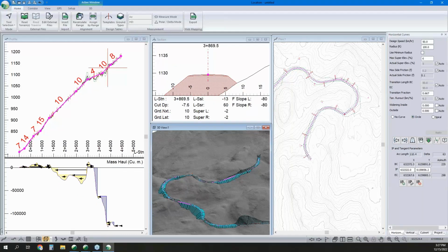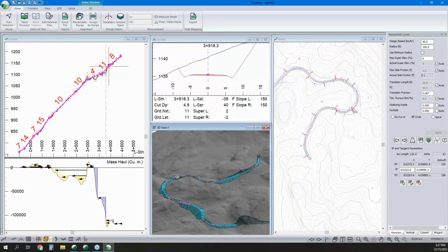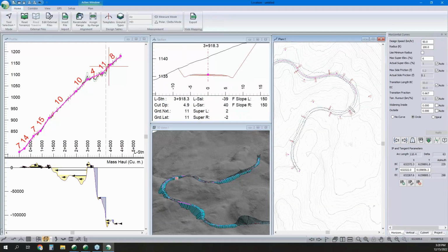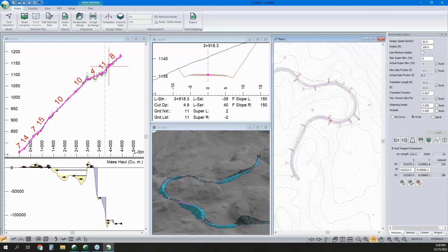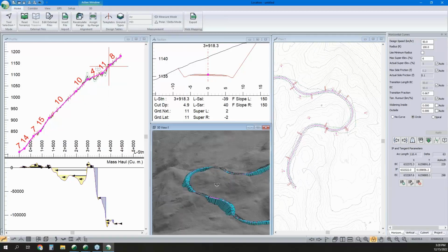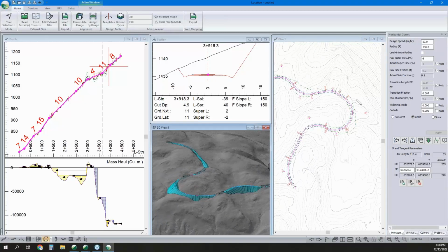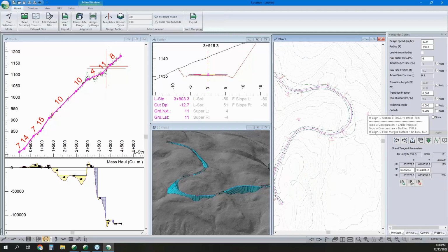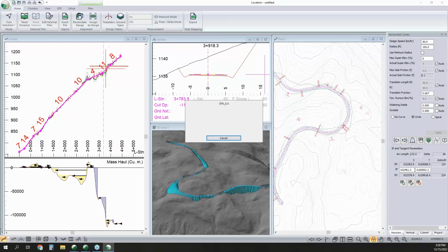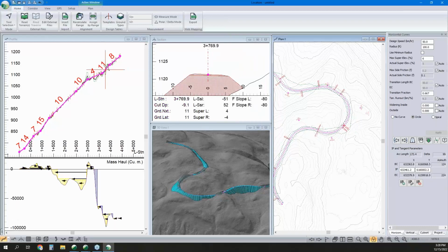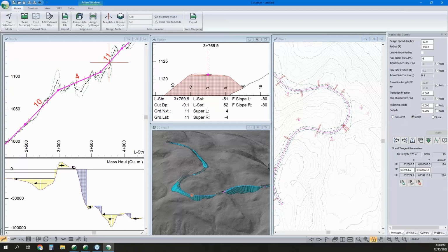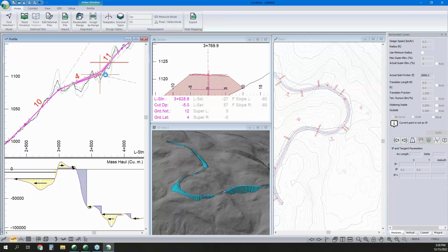And we can. And we can see here my little dashed green line, that's my slope stakes. So I can see I'm filling out even without looking at my 3D view. Perhaps I want to make some adjustments so we don't end up spending a fortune on fill material. Better, not ideal, but I can also drop my grade.